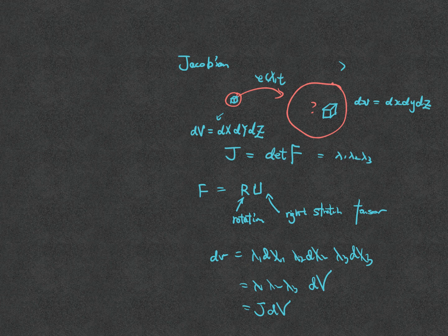The Jacobian takes into consideration the nonlinear mapping. But what is the relationship between the trace of epsilon and the Jacobian? Actually, they can be related by the natural log. The log of this is equal to the trace of the infinitesimal strain.